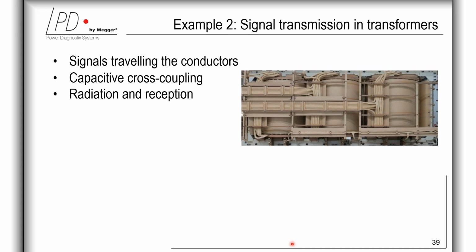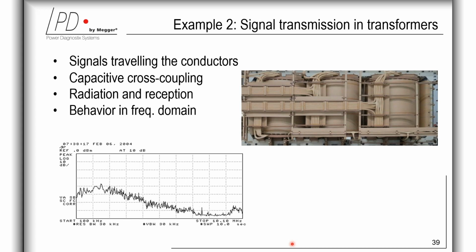In this way, this effect partially compensates the effect of trapping signals because of the mentioned reflections. In large power transformers, there are many unshielded leads of different coils that are laid and also meet at different places. These unshielded leads then act as an antenna for both radiation and reception of the high-frequency partial discharge signals.